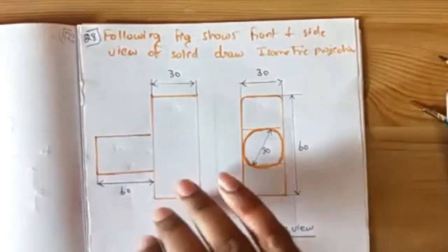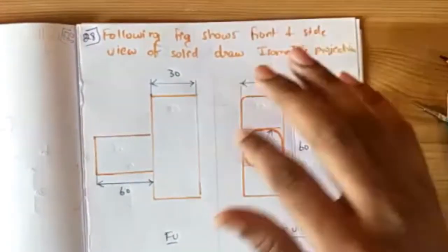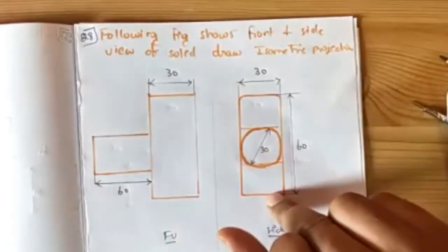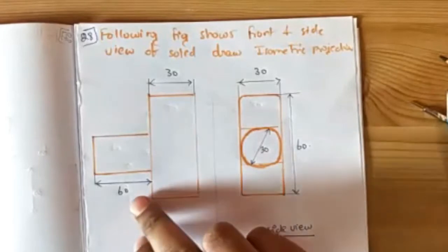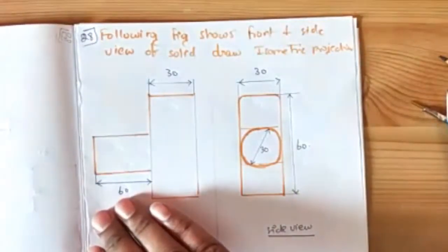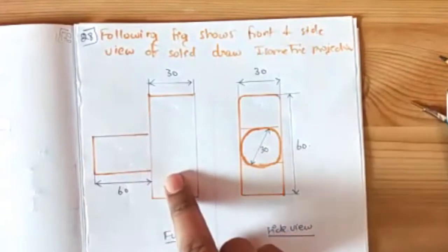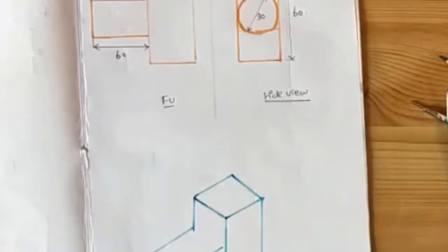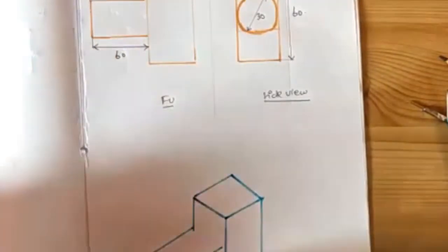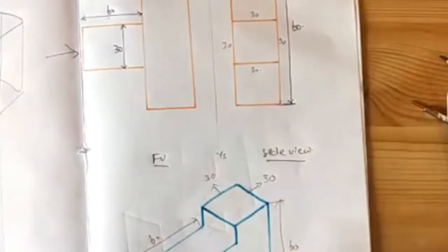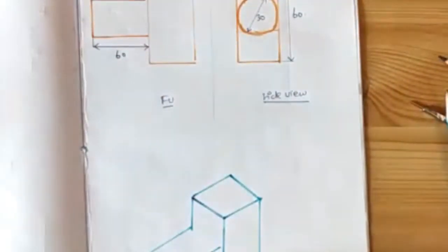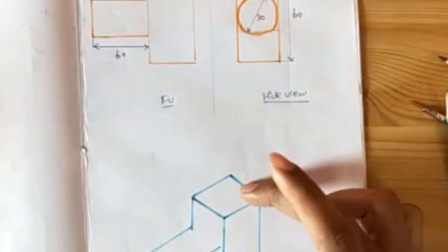Can you see the next problem, the second problem? What is the difference between the first problem and the second problem? See, the prism is the same. What was the prism which was given? It was the same, but here the projection which is being done from the middle of this vertical prism is nothing but a cylinder. You can see a cylinder. A cylinder is being projected. In the previous problem, there was a prism which was projected from the middle of this vertical prism. But in this case, a cylinder is being projected from the middle of the vertical prism.